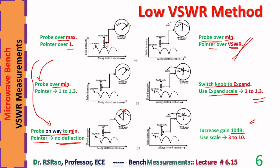Then move the probe to minimum. When you move the probe to minimum, the pointer may have a position like this. Whatever is the reading against the pointer over the scale 3 to 10, we have to use the 3 to 10 scale. Not the 1 to infinity scale, not the 1 to 1.3 scale, but the 3 to 10 scale to measure VSWR.